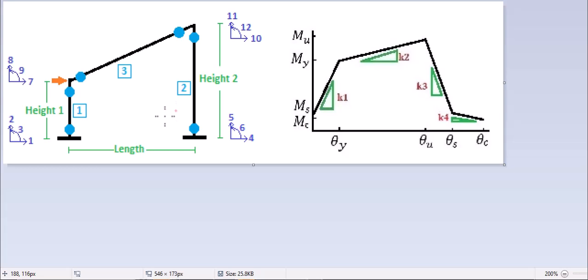And we are going to increase the force in degree of freedom number 7, and in each step we are going to evaluate the section moment, strain and capacity to see if plastic hinge happens in each increment or not.